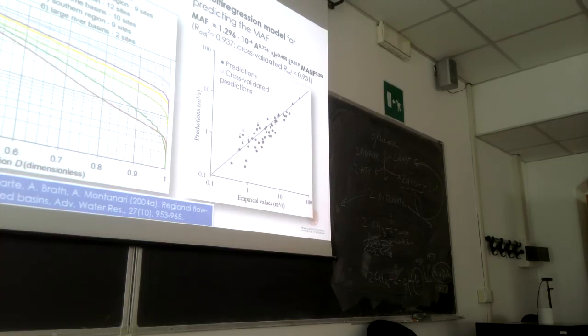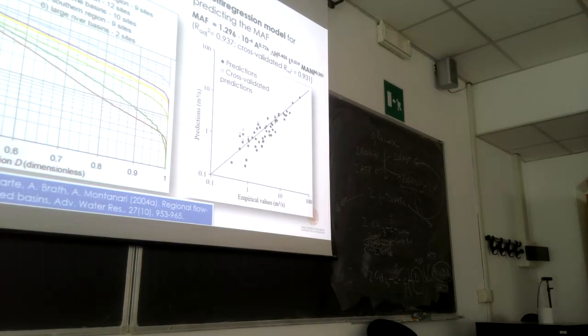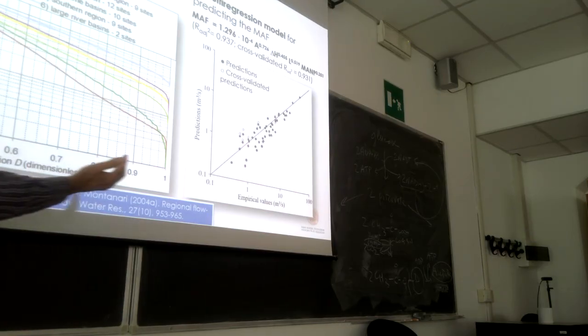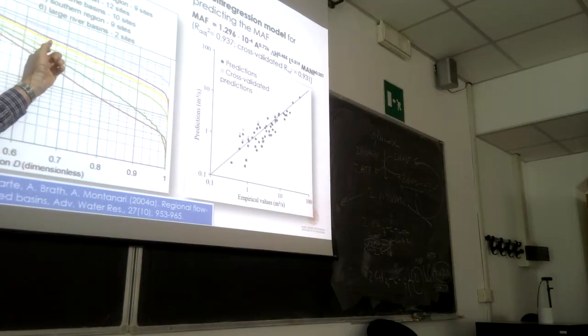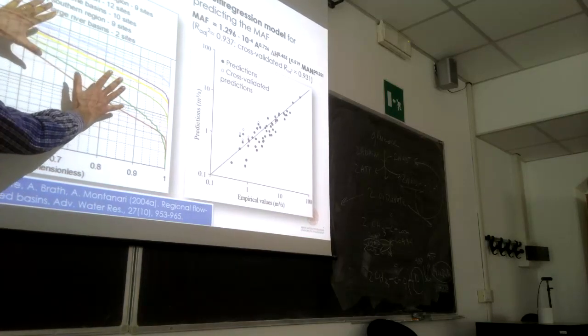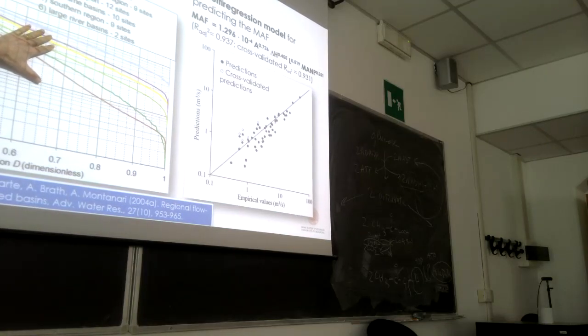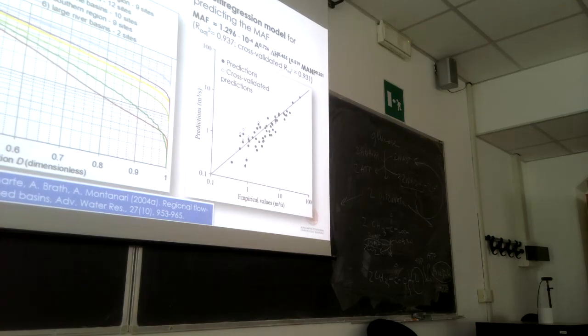So the electric power plant managers are interested in the right portion of the flow duration curve, intermediate flows and low flow. This is the portion that is the most interesting to them. Also because when the flows are high, you can produce hydropower, right? You have water. Whereas you are concerned when the flows are low, if you want to quantify the hydropower potential, right? So high duration. So they expressly indicated interest in this portion of the flow duration curve, from 0.3 to 1.